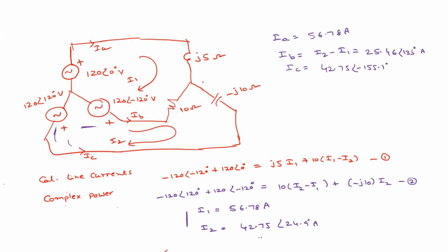So next, these are the line currents, right? So how to calculate the powers, or the complex power? In the earlier case, we have some formula, right? Root 3 V line, I line, cos theta. This is the power formula. And Q is the same thing, but sine theta. And we have complex power S equal to P plus JQ, right? Agree?